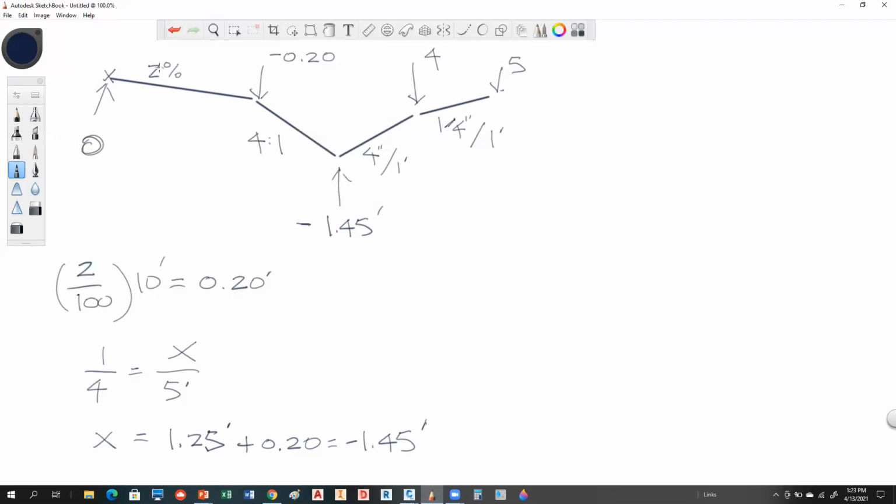Yeah. So we're going to calculate that number 4. What we did here was for 3 right here. This was for 2. We're going to do it for 4 now. So Jake, you just told me it's 4 inches of rise per foot. I'm going to put this in feet per foot, okay, to keep the units consistent, right? Yeah. So what I want to know then is what is the rise in feet over a distance of 5 feet? So that gives me an X value of what?